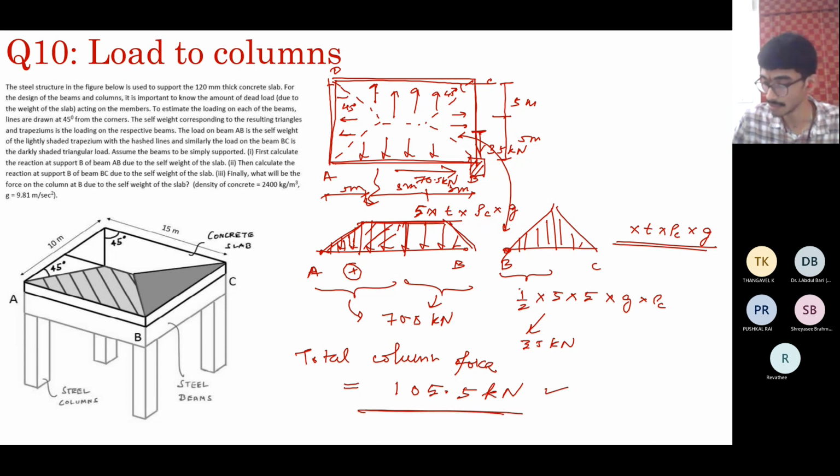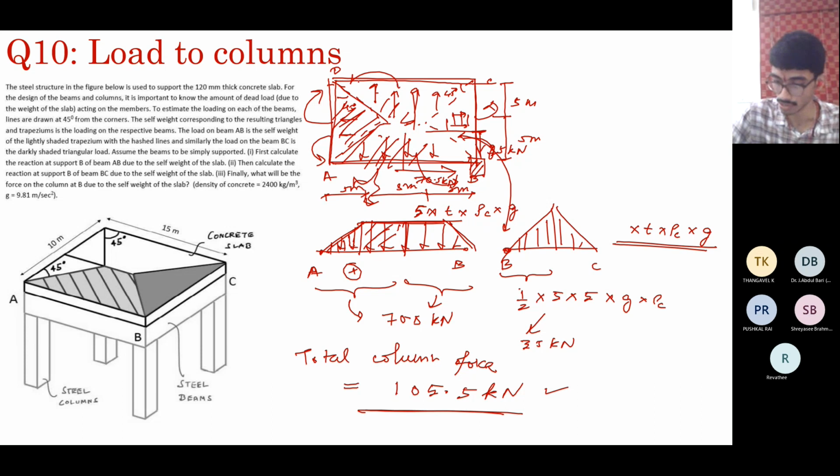So you can check this. This is a simple problem. You just have to find the area under this, divide it by half, and take it to each of these steps. Same way, find the area under this, divide it by half, take it to each of these steps. So each of these will receive a load of half from this and half from this. So this is the last problem for the day. Thank you.